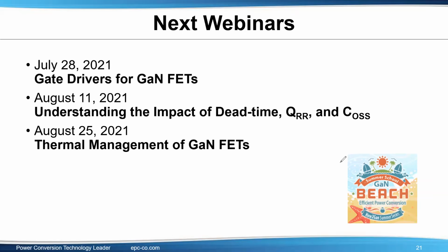Will any of these GaN devices be offered in standard packages like TO220 as a drop-in replacement for the field? I mean, you can expand on this, Marco, but really, regardless of package, they're not really drop-ins ever, right? Right. The main point is GaN FET is not a drop-in replacement of a MOSFET.